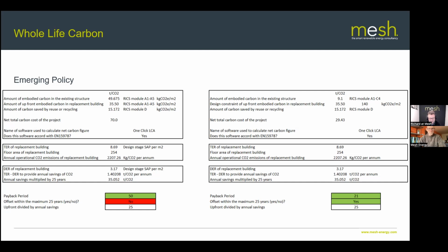But at the same time, this carbon calculation is just one aspect of the project. So if, say, for example, there are structural challenges or material challenges with the existing building, and it's been built in such a way that it's impossible to retrofit. I mean, there are some materials out there that literally it's like working with sandcastles. And so it becomes part of the consideration.